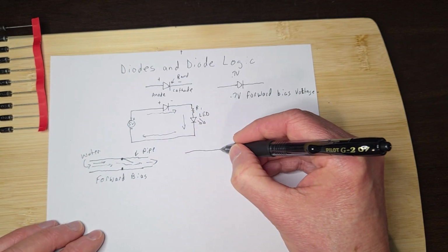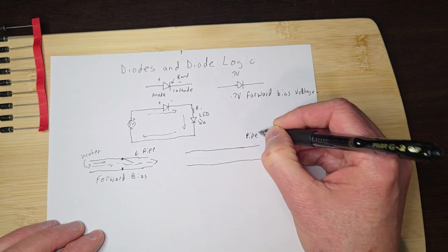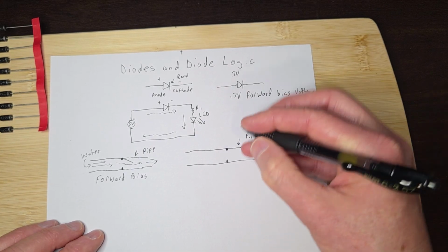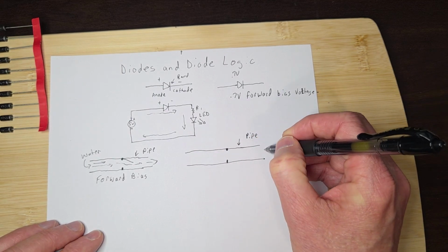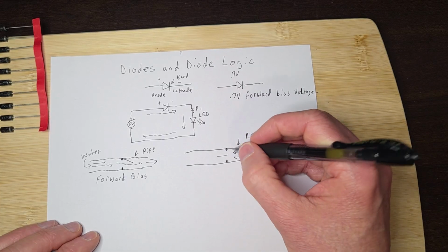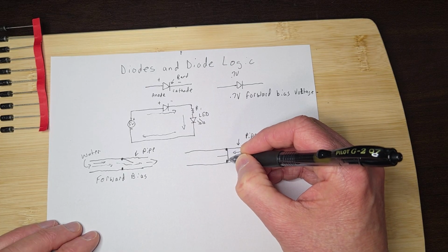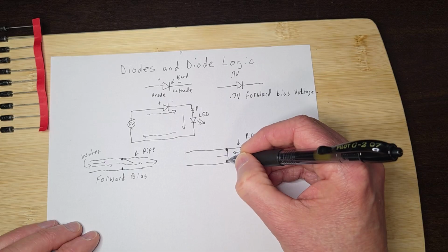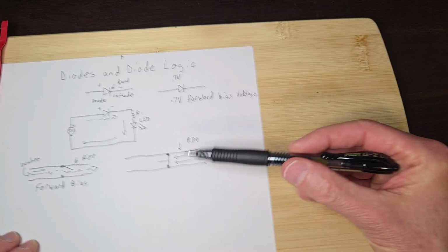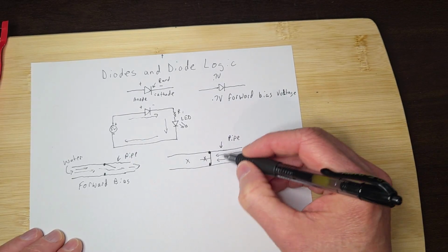But let's say you have the opposite situation. So here's your pipe again, right here. And let's say we have our little stop, to keep the valve from going this way. So let's say we have water going this way, and it's trying to shoot through there. But what's going to happen is the force of that water is going to push that little door down. If you're real mechanically inclined, you'll see what I'm talking about. Water's coming in this way, and it's going to really push against that. And so now there's no water flow here at all, and the water's just going to stay backed up.